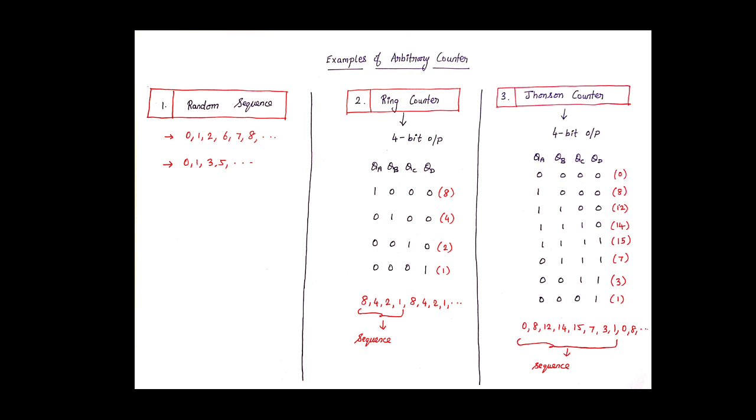We already know two counters, the ring counter and the Johnson counter. What is a ring counter? If n flip-flops are connected in SIPO order, then only one flip-flop is going to produce the output as 1, and the remaining ones are 0. There is only one data bit, and that one data bit is circulated again and again in a circular way throughout the shift register. That is called a ring counter. What is the order for that? In terms of number, that is a mod of n.